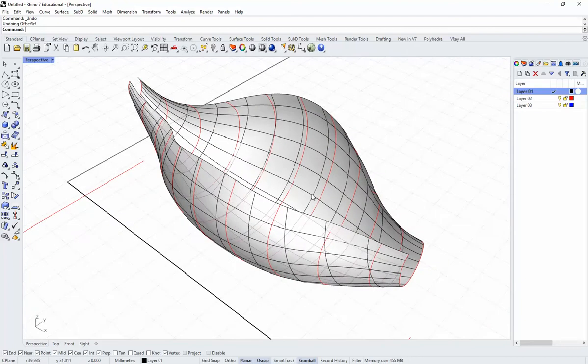Now, there's a couple different ways you can go about adding thickness to this. You either offset in or offset out. If you offset in, we'll explore one option for that, but it's assumed that the current dimensions you have here are the maximum. If you offset out, it's assumed that you've already accounted for the material thickness. Which one to choose sort of depends on the kind of surface you have, and how to do the offsetting.